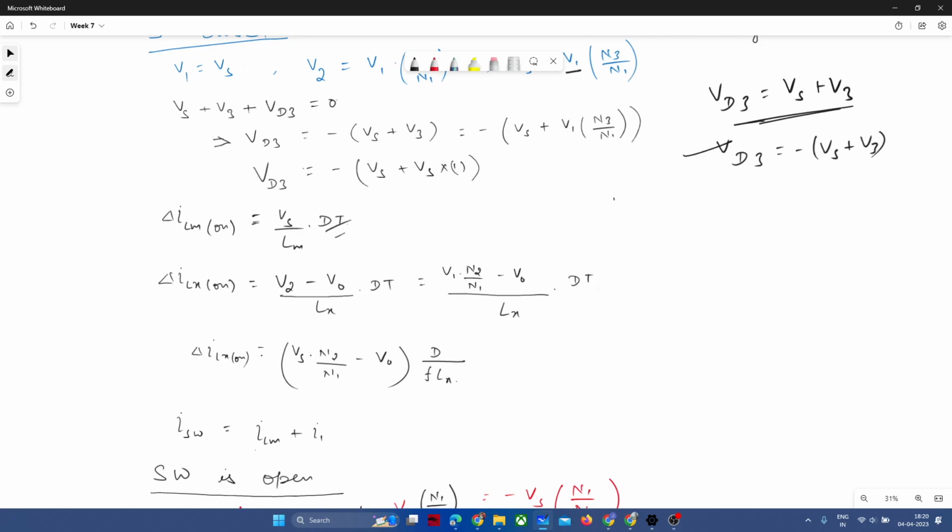So the material is available. Materials which produce higher values of maximum BM are available. Only the cost is the limiting factor now. Yeah, many people shift to air core. Why? Do you have any idea? No, sir. I just read somewhere that there is no saturation problem, sir. Yes, there is no saturation problem. There is no loss.